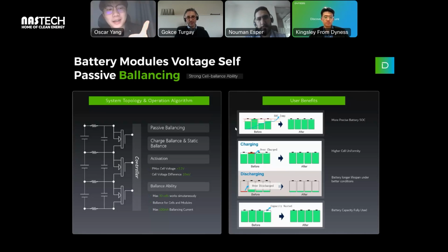This is the first aspect. For the second aspect, we as the manufacturer recommend that when you are using a battery, set the minimum discharge battery SOC to 20% rather than 10%. 20 to 100% is a better range to protect the lifespan.